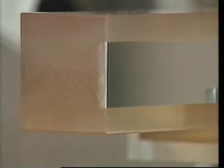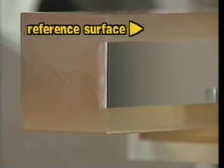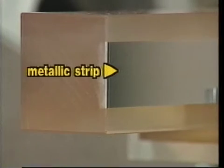Zero-Dur is a glass material with a very low coefficient of thermal expansion. This characteristic makes Zero-Dur a very attractive material for high-precision applications requiring dimensional stability. The reference surface of the straight edge has been ground, lapped, and polished to be both smooth and flat. The error in the straight edge is specified as 45 nanometers over the 300 millimeters of length. The reference surface has been metal plated to facilitate use with a capacitance gauge.